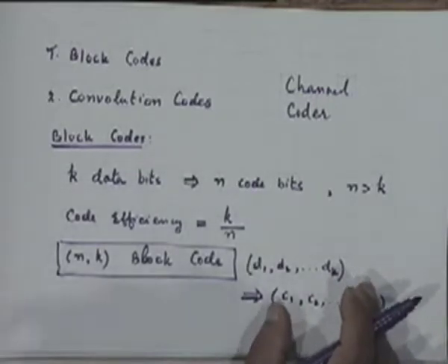That's right. There are some proposals and schemes where people have tried to argue, why not use a redundancy that is inherently present in the source itself to carry out error correction and detection. But that kind of scheme has not been perfected yet. The theory of those kinds of ideas has not been worked out very nicely. So at the moment we have segregated the two problems, and this is how most real life systems work. The source encoding process is decoupled from the channel encoding process, and the corresponding decoding process is also decoupled. Okay, so does that answer most of the questions that were raised?